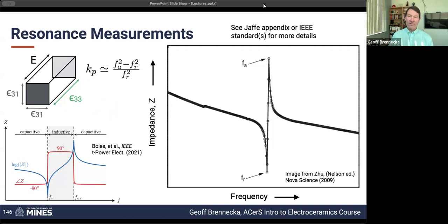If you look at the resonators that are in the phone, they are irregular pentagons from the top, because they want to take advantage of the resonance through thickness, which gives you the highest frequency. So it's meant to be a thickness mode, but avoid any of these spurious contributions from lateral modes. And so the easiest way to do that is to make a shape that doesn't allow easy bouncing of these lateral modes from an acoustic perspective.